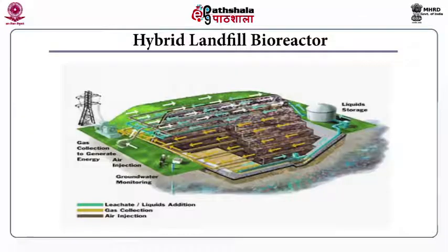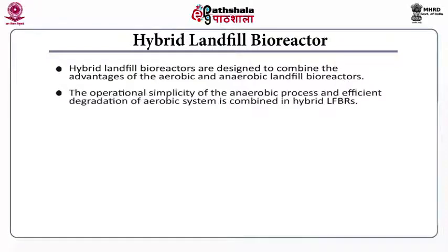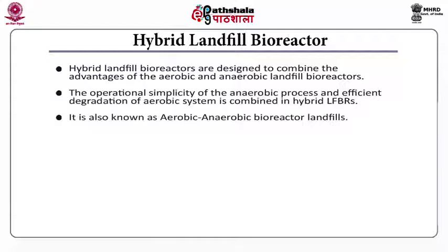The third type of landfill bioreactor is a hybrid landfill bioreactor. In a hybrid landfill bioreactor, it is generally designed in a way so that both aerobic and anaerobic degradation occurs within the reactor. The operational simplicity of anaerobic process and efficient degradation of the aerobic system is combined in this landfill bioreactor. It is generally known as aerobic anaerobic bioreactor landfills.